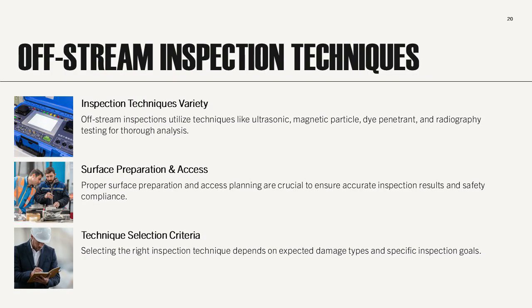During off-stream inspections, inspectors can employ a wide range of techniques, including internal visual inspection, ultrasonic testing, magnetic particle testing, dye penetrant testing, and radiography where applicable.